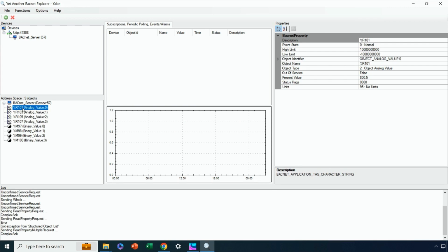It doesn't show a variable name. It shows as %R101 because in this case that was the register this analog value was mapped to. They're going to be consecutive, and because they're floating point, each one is going to take up 2 registers. So we've got 101, 103, 105, and 107.